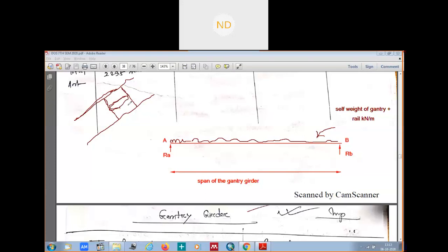Okay, now on the crane girder, you see here, this is the crane girder, sorry, the gantry girders here, these things. These are your gantry girders, which are simply supported beams. Then we have this as your crane girder. Now, on the gantry girder, you see here, this is the crane leg of the crane girder, here one, here one. So this is obviously going to move in this way and this way. So now where we get the shear force maximum, we had the load when we were checking for the crane girder C to D from here to here.